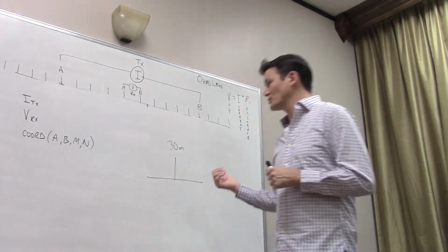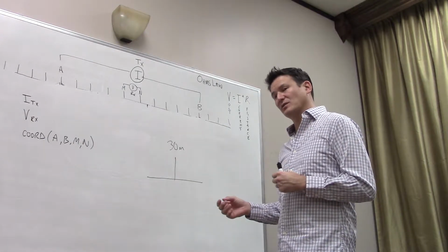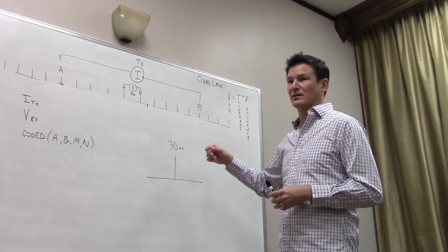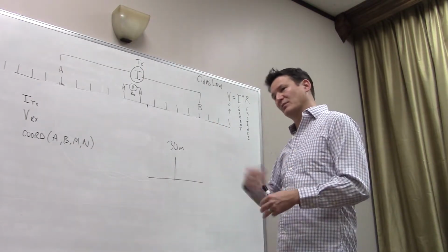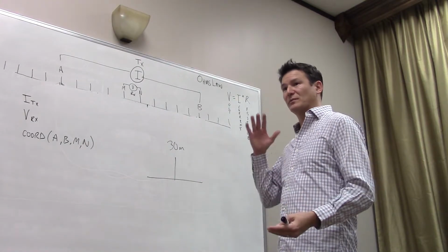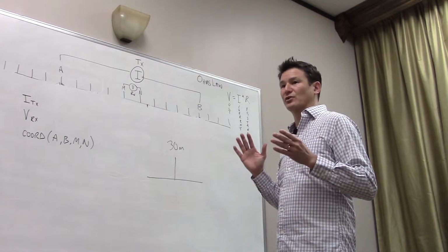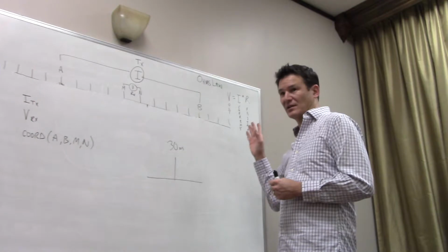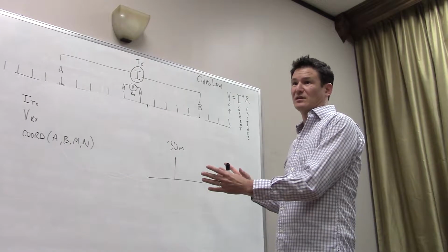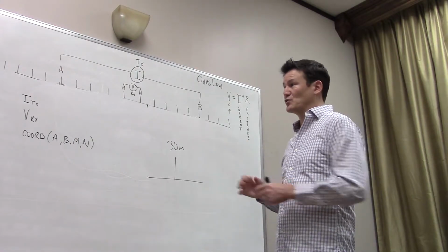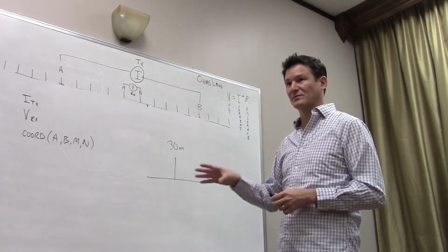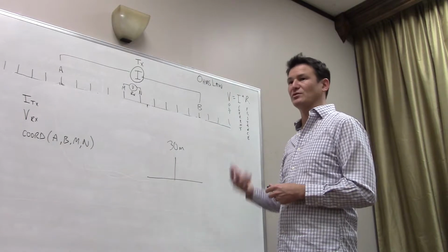So the next thing we did was we put electronics out at the electrodes that would automatically turn one of these stakes into either AB or MN, so that we could make all these different measurements. And then we had multiple channels so that you could do it very quickly. We tried to abstract the technology away from the user, so you didn't have to really know what you're doing other than just set up an equal spacing. And then we designed software that takes this data and calculates the resistivity response of the Earth for you, so you end up with a nice, beautiful picture where you can see some structure in the Earth associated with the different types of rock types, materials, and minerals.